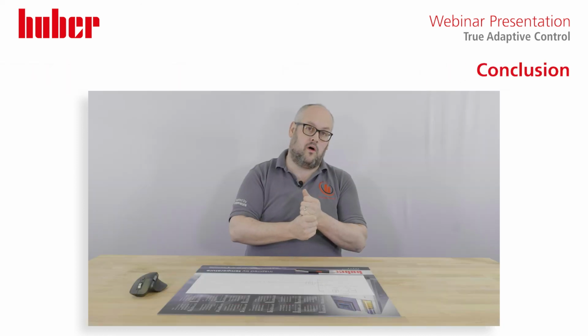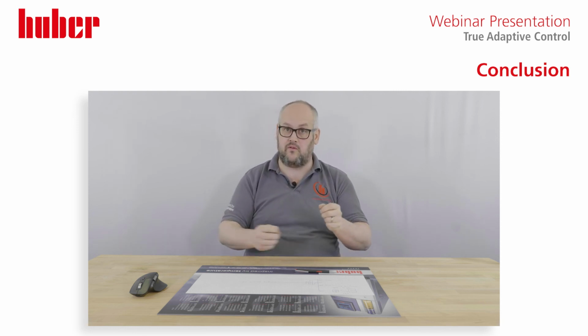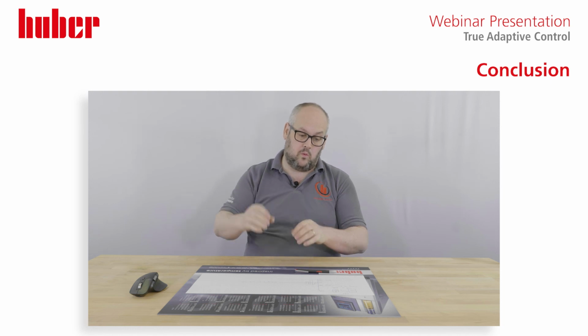So what I've actually discussed here is application testing where we're using a process probe. Why have I done that? It's a bit trickier, I'll be honest, because we've got more variables. You do have an option of testing and tuning with just the internal temperature probe, and I won't lie, that will complete really quickly and it'll give you good results.